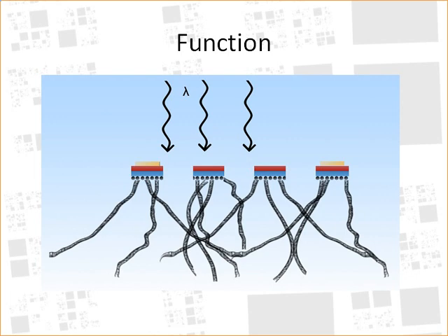Thus, the physically absorbed surfactant serves as a long-term memory, where those layers or channels of carbon nanotube which have higher concentrations of surfactant adhered to them are able to communicate more effectively with each other. The amount of incident light can be varied or pulsed in order to set up different modes of operation in the neural network.